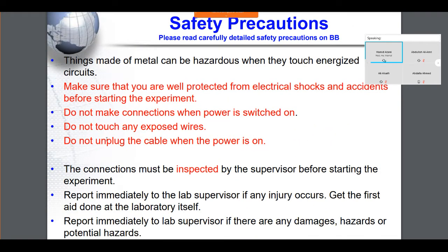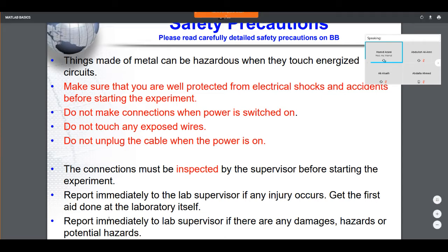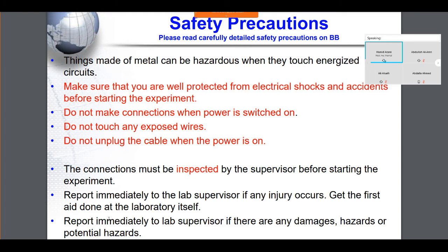safety precautions here, they are written in a general way. Usually, just to let you know, as electrical engineers, I'm talking in general here, not step by step what is written here, but as engineers, we should be aware about the electricity we are using, and we have to be aware about the places where we have a push button, emergency stops. Once we go into any area to work, you should be familiar with that area before you start working in it. In terms, as I told you, of the location of those emergency stop buttons, which type of current you are using there, the level of that current, the type of current or voltage, AC or DC, the level of that one.